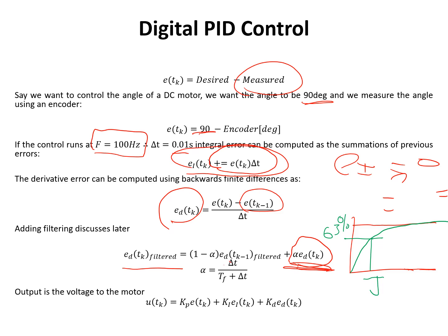So now what we can do is we can actually develop our alpha value based on the time constant. Here I have the time constant as TF, but that's the same quantity. So based on how much delay of the filtering you want to add, because again, as we said previously in filtering, the more filtering you add, the higher the delay of the signal. So if we filter the signal at this quantity, we might get a cleaner signal, but still maybe noisy. If we add filtering, we might get a cleaner signal, but a higher delay. And again, there's a compromise between these two.